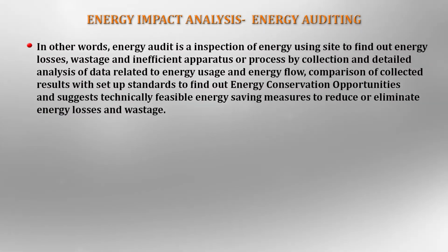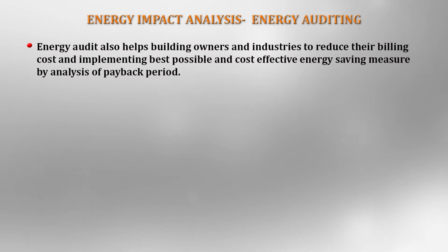In other words, energy audit is an inspection of an energy-using site to find out energy losses, wastages, and inefficient apparatus or processes by collection and detailed analysis of data related to energy uses and energy flow, comparison of collected results with set standards to find out energy conservation opportunities, and suggest technically feasible energy saving measures to reduce or eliminate energy losses and wastages. Energy audit helps building owners and industries to reduce their billing cost and implement the best possible and cost effective energy saving measures by analysis of payback periods.